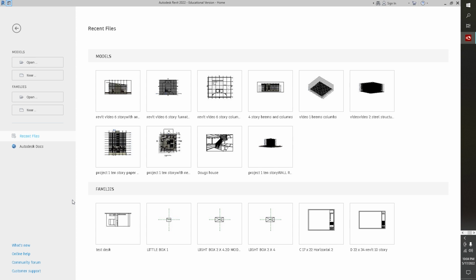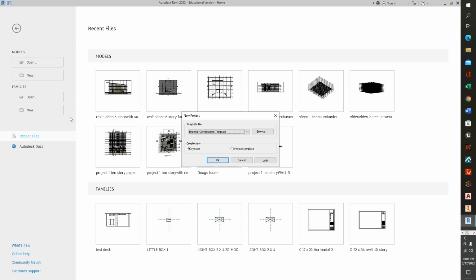residential building started. So we could go up here to File, New, create a new file, or we could just press Control N, like in many of the programs that are out there. Control N should give us a new file from that particular menu here. So we have a bunch of different models it could be. Imperial Architectural is not a bad one to start off with. I like it myself. The structural template, we'll go with Architectural.